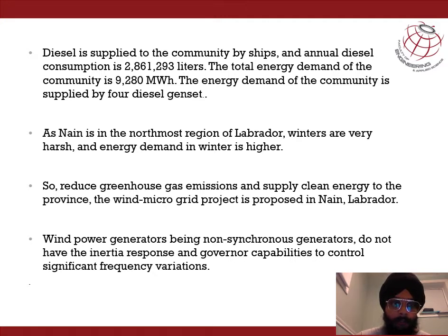So in this project we have focused on the variable droop control method to regulate frequency by controlling active power, and MATLAB modeling is used to simulate the effect of the proposed 2.3 megawatt wind battery facility in Nain, Labrador, along with the three diesel generators that are currently operating to fulfill the community's energy demands.